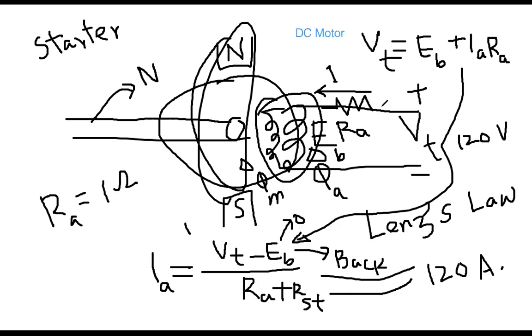So therefore, here in series, you have to add that starter resistance, RST. In fact, in the lab, when you will be doing the experiment, you don't need to do anything. These things are internally designed; automatically at the beginning of the operation, this will be active in the circuit. This will automatically come in series with the armature. So then it will protect your motor.